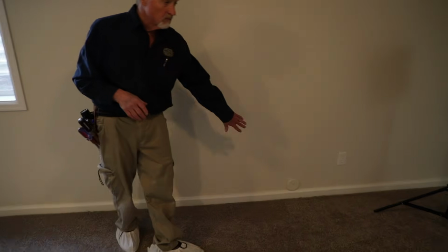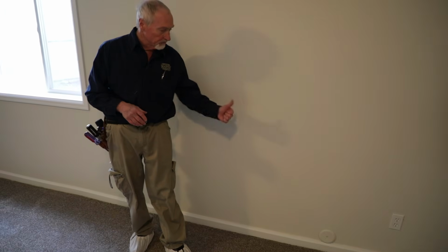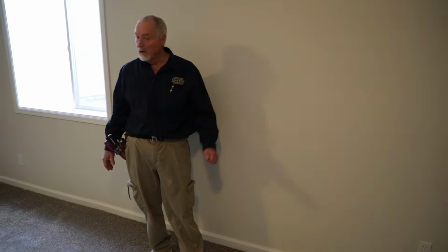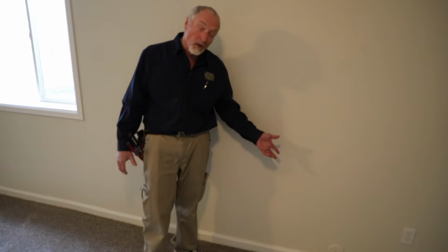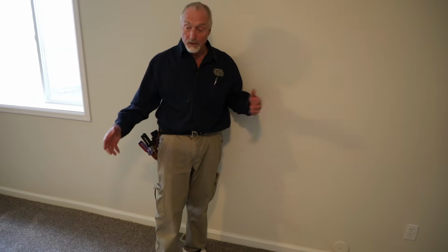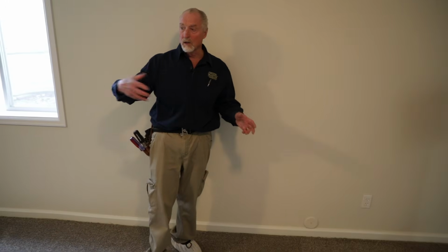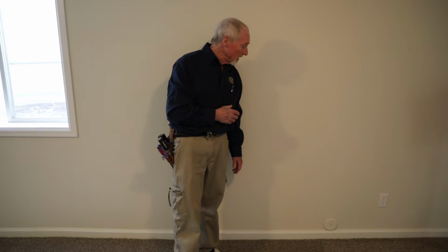Same thing, clean out cover. So good, required. If you do happen to have reason to believe that there's no access to a clean out, or you can just tell the way they finished, maybe looking inside a wall, that there's no access to it, call it out. It's a defect. And now we'll go look at a bathroom.